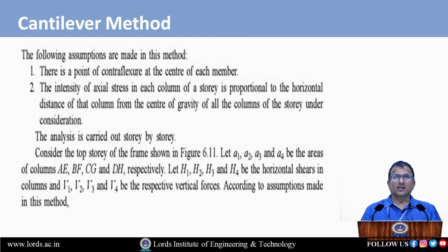Coming to the second assumption that we follow to analyze the frame by cantilever method: the intensity of axial stress in each column of a story is proportional to the horizontal distance of that column from the center of gravity of all the columns. How we can evaluate the center of gravity of all the columns, we will discuss after that. That's why the analysis of the frame is carried out story by story.